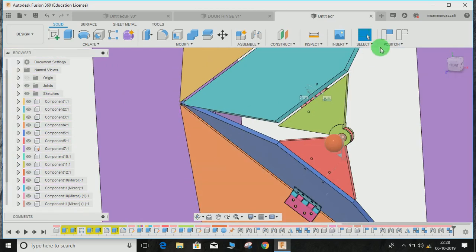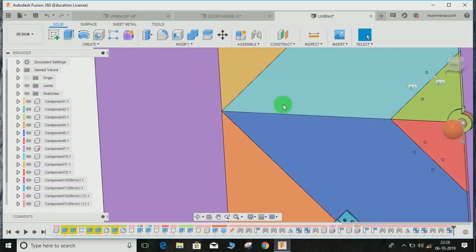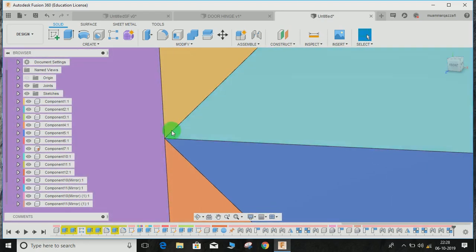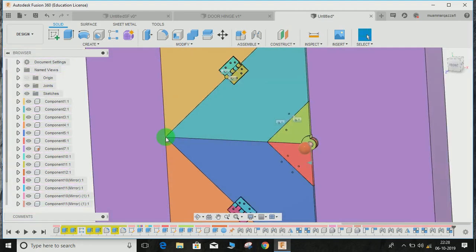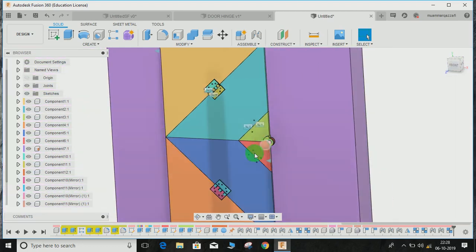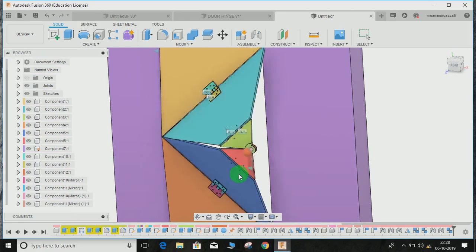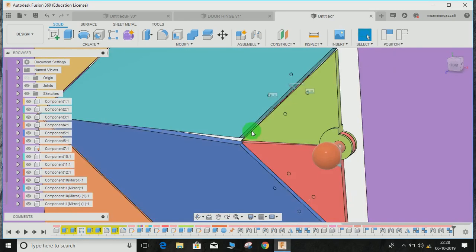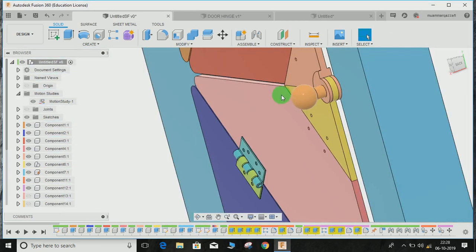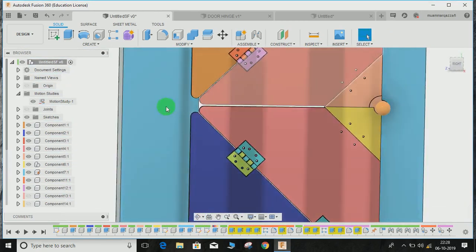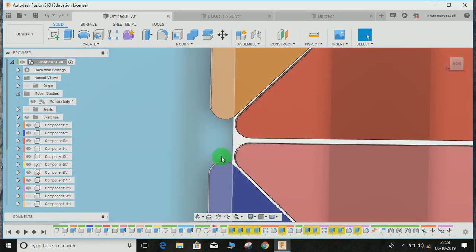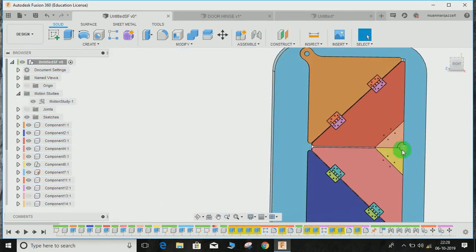So now the last thing that needs to be done is you have to give a fillet on each and every corner, so that it may avoid intersection while opening and closing of the door. Another thing is to offset these spaces by 10 mm, so that, as I did here, you guys can see I have given a radius which actually looks beautiful, and this avoids the intersection while opening and closing of the door.